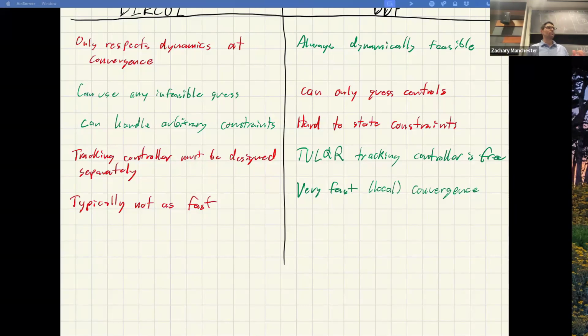Yeah. So fun fact, we saw how the LQR QP, Riccati, is basically a sparse solution to that. So that actually carries over. You can write an SQP method that uses Riccati as the internal matrix factorization solve, which people do for speed. So there are close connections here all over the place, but generally speaking, it's easier to make DDP go fast than it is to make dircol go fast.